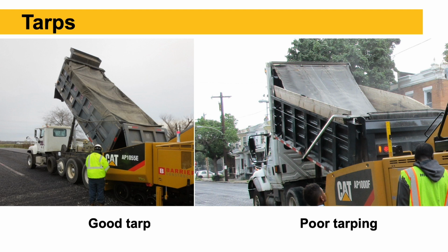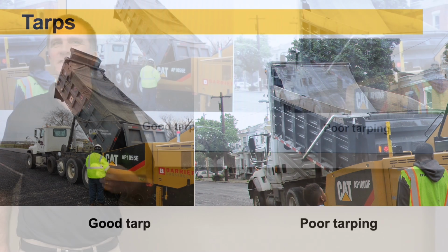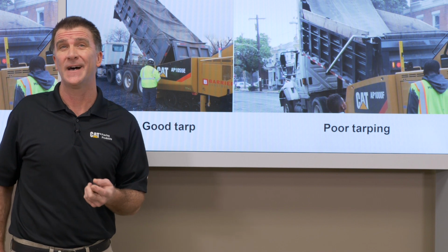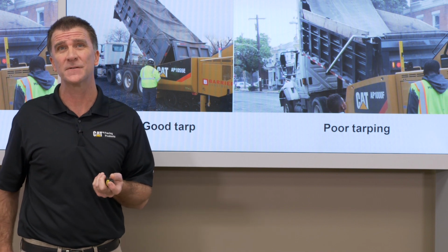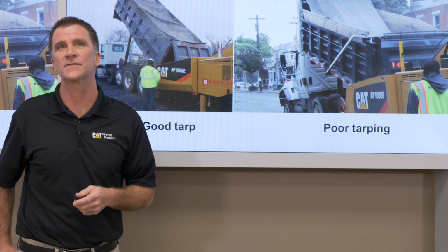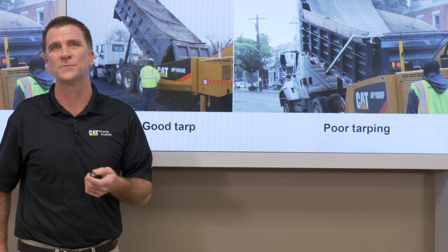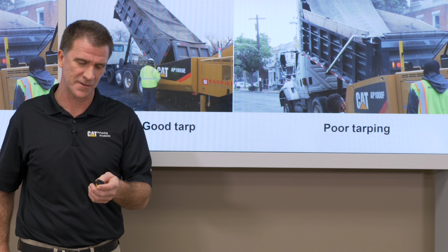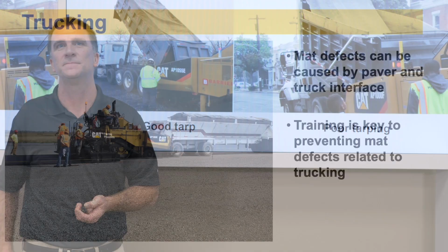So there's good tarping, there's poor tarping. As far as material goes, I tend to prefer the canvas tarps. They're a little heavier and they actually kind of sit on the mix and just retain the heat a little better than some of the other materials.